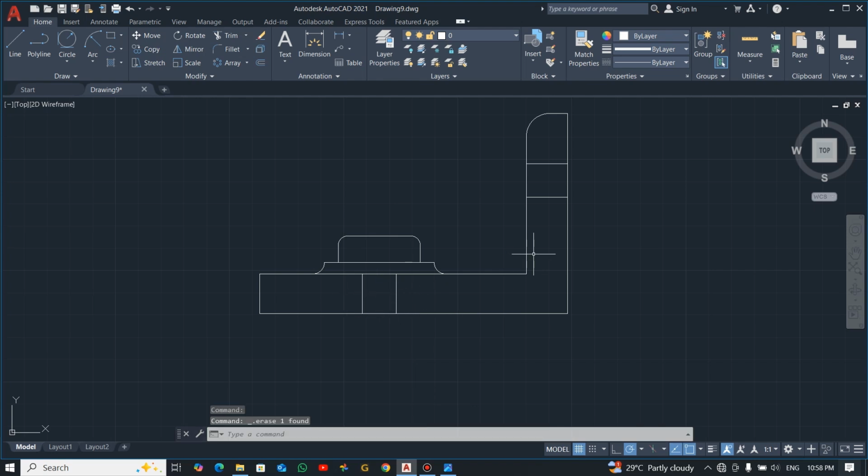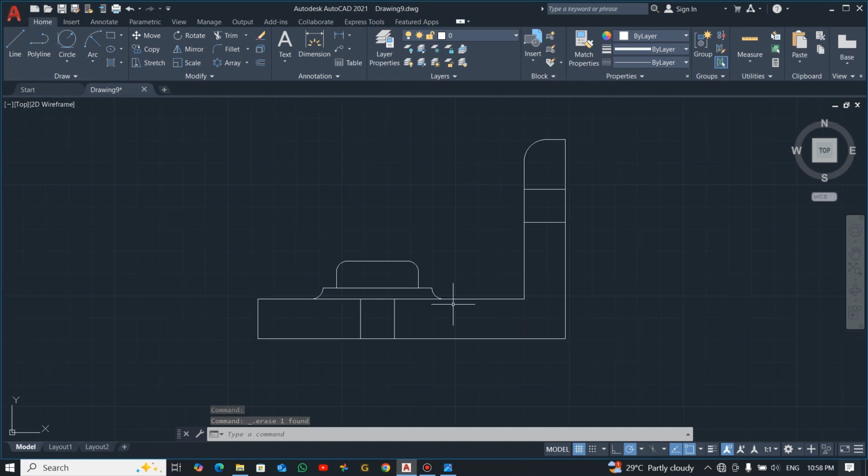So you can see we are done with the work, but there's a center line here. So if you want to put a center line, you can just enter CL and then you press enter. Now it will ask you to select first line, so this line, and then the line will come. Okay, press enter again to repeat, then the center line will come, but you are not seeing it as a center line because you need to stretch before you can see. Good, even the same thing also here, stretch a bit.